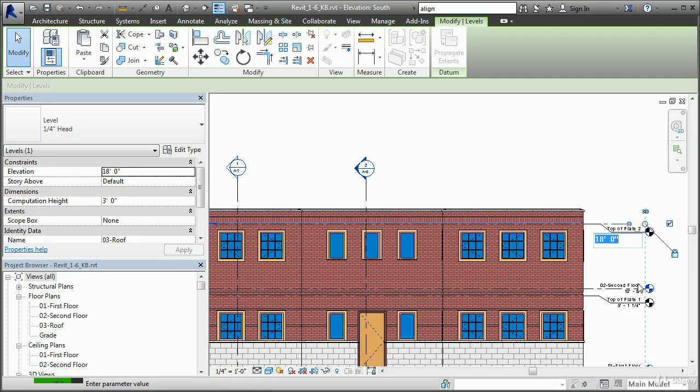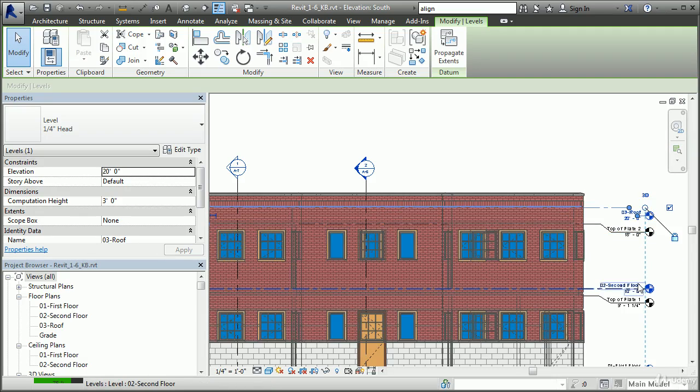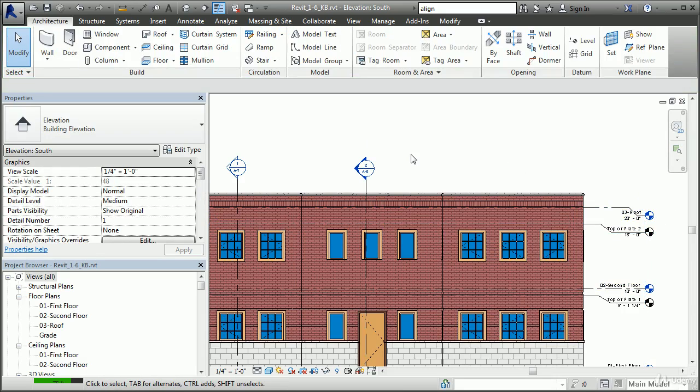So just by changing a single value here, we can adjust the entire shape and size of the building. In a regular CAD drawing, changing the position of an element such as a window by stretching it will also update any associated dimensions. In Revit, this is also true, but it's taken a step further, as you can actually select any dimensioned element such as a door or a wall, and its dimension values will be highlighted. Modifying that dimension value will actually modify the position or size of the dimensioned element.